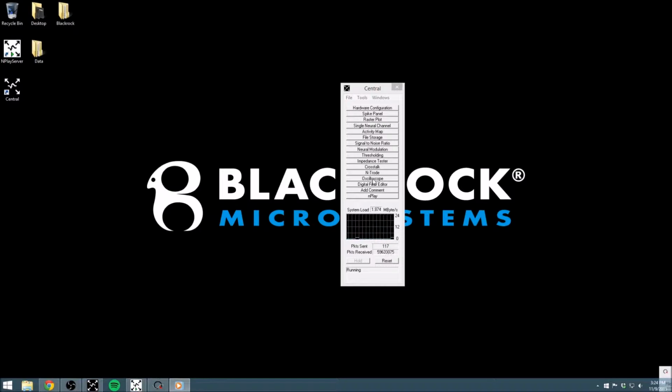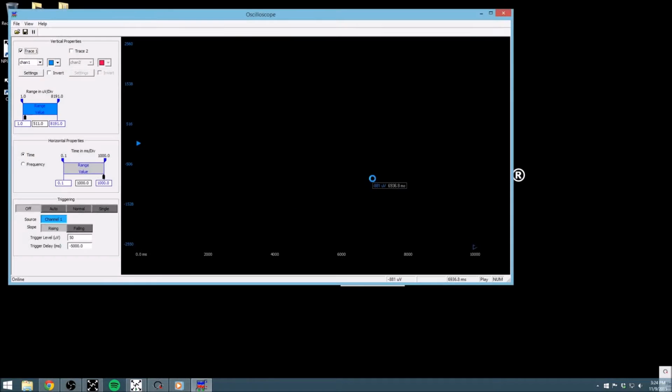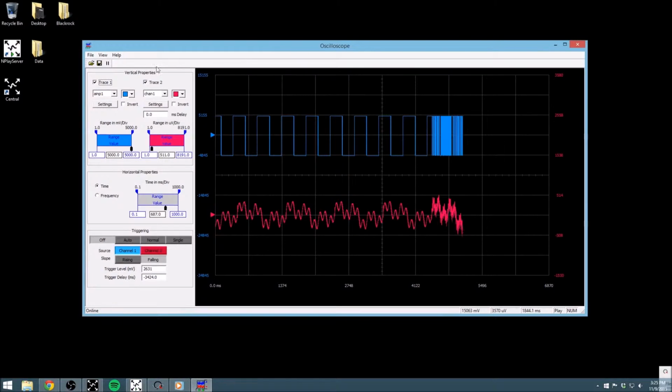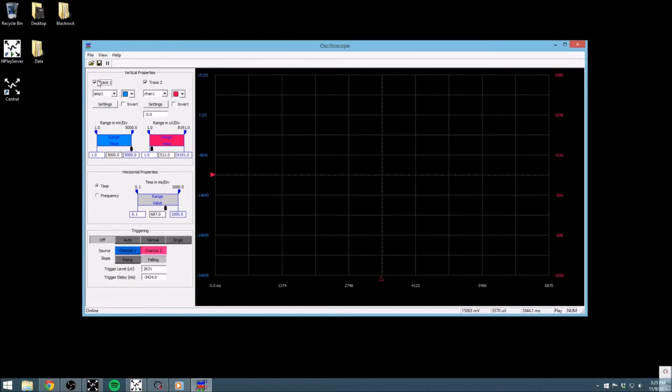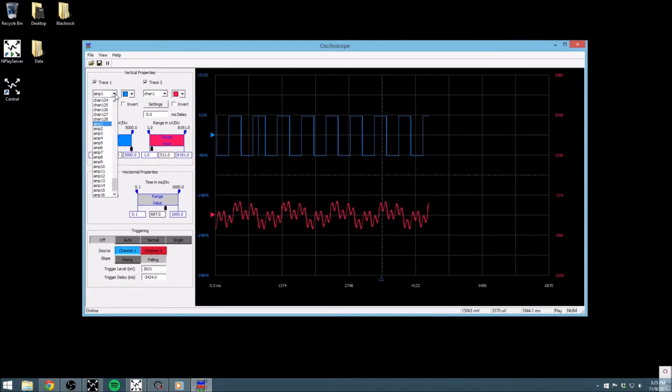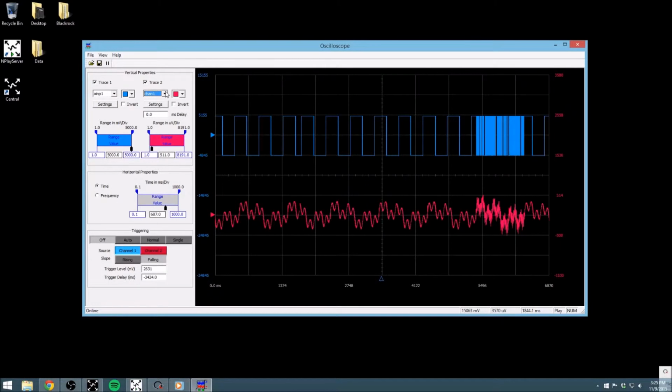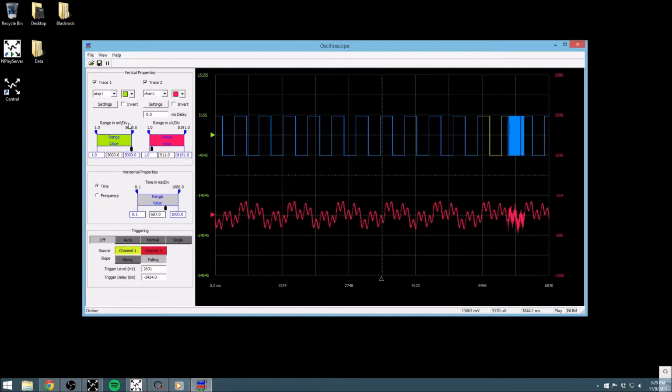It enables you to look at the signals more closely and with greater time resolution than many of the other central modules. This oscilloscope is a two-channel oscilloscope. Each channel can be enabled separately by using these checkboxes at the top of the window. After enabling a given trace, we can use the drop-down to choose the channel represented from any of our available analog inputs, which include our amplifier channels and B and C inputs on the front of our processor.